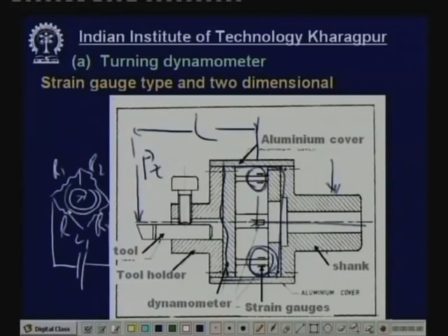It has to be amplified and rectified, and then read on a unit. The Wheatstone bridge is inside, and the rest is put into an instrument called the strain measuring bridge, where the EMF, magnification and amplification are carried out.